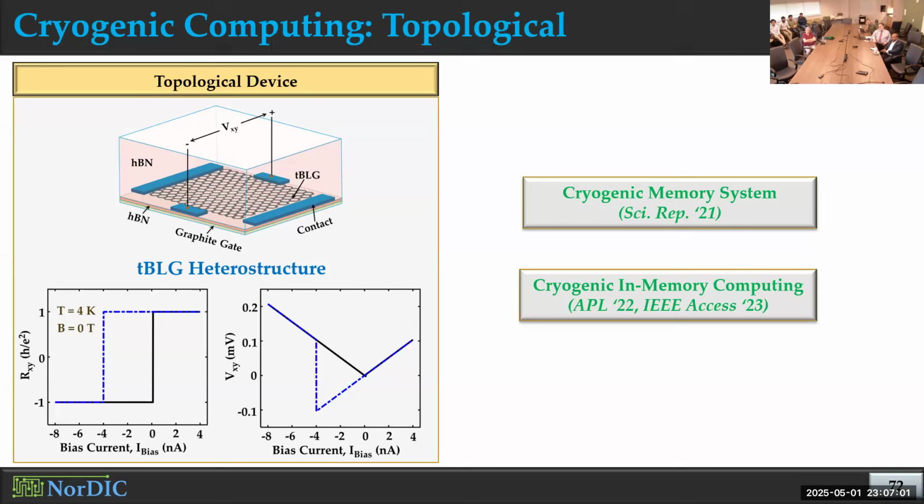But as I explained, the heater cryotron has high resistance. People have shown mega ohm level resistance, and that's also used as an interface between CMOS and superconducting circuits in different papers. But the challenge is, again, we need high voltage because of this ferroelectric. I was just pointing out that higher voltage is not necessarily higher power. It depends on what's happening with the current. Yeah, obviously, because in the heater cryotron, when you have a resistive state, you have to apply the suitable current to get that voltage. So that will actually increase the power.